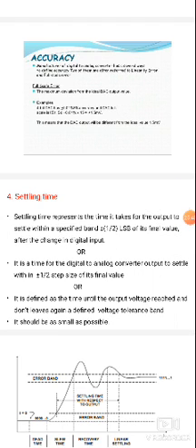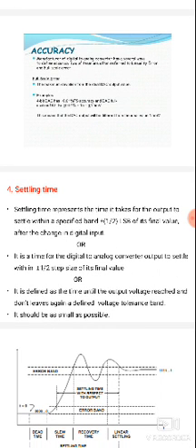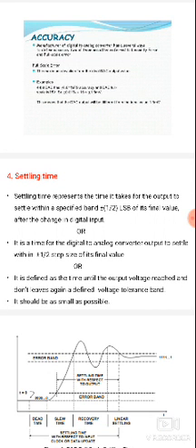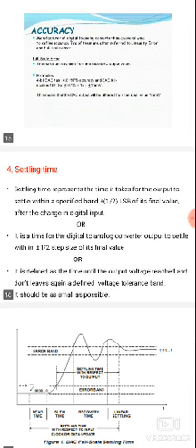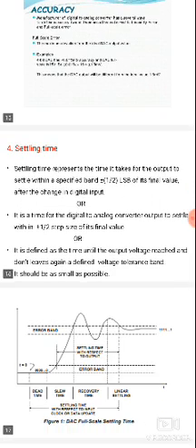We do not get exactly 15 volts; it will be either incremented or decremented. Why? Because we have the full scale error. So 0.01% is multiplied with 15, which changes the output by plus or minus 1.5 millivolts. So the output of the signal will change by plus or minus 1.5 millivolts from 15 volts.